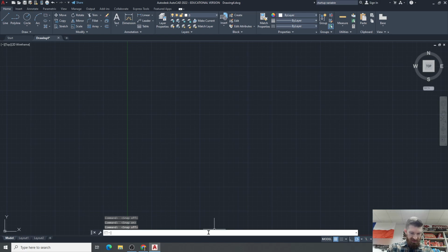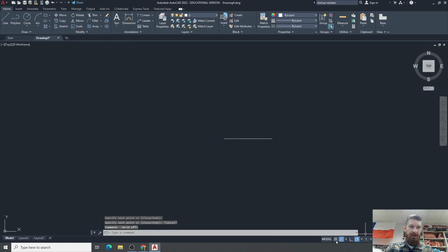There's also grid settings, so you'll notice there's a grid behind the screen. You can specify the spacing of the grid. I don't know what these little boxes represent right now. It looks like the default value is 1/2 inch. I'll set it to 1 inch. That way it matches my snap settings, right? So now it lines up. These little boxes are 1 inch, right? And then the grid is right down here. You can turn it on or off using F7. There's F7 for grid and F9 for snap.